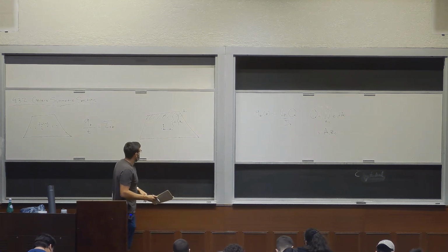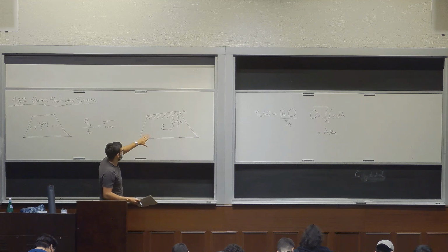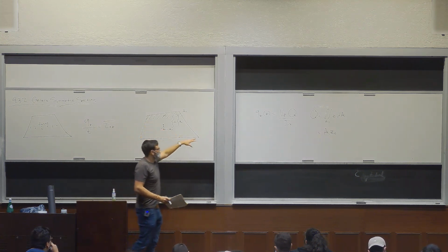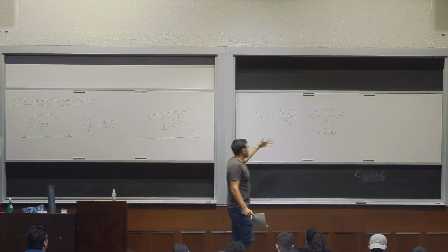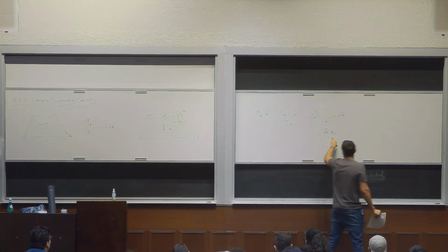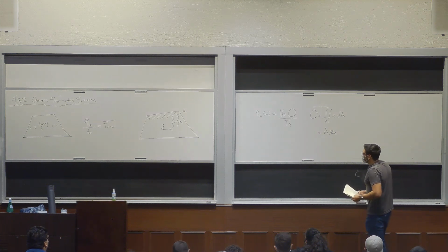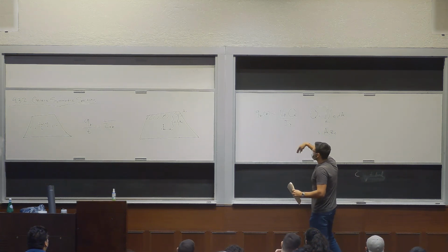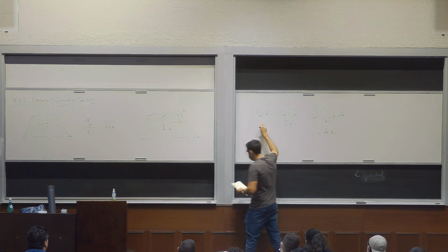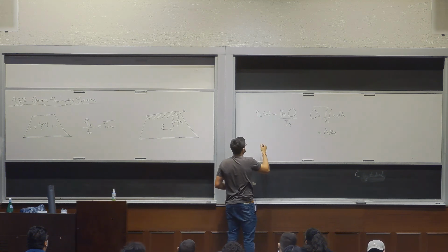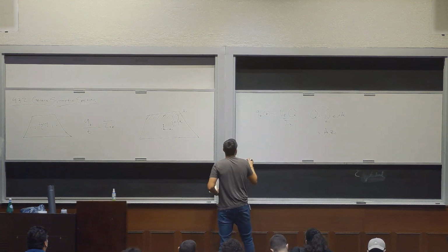So you would take this shape, find the centroid, easy enough, cut it at whatever location is relevant to whatever you're looking at, and then at that location you'll have an A and a Z position. You'll have to find the centroid of the new area as well, and then you're given all the other values, and you can solve for Q. Okay, and now that you've solved for that, then you can easily solve for tau xz.